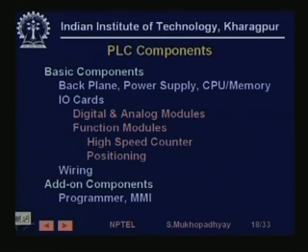So obviously there is wiring, and then you need two other separate devices with the PLC mainly for interacting with it. One of them is a programmer using which you can download the PLC program, or you can see how variables are getting changed, and the other is a man-machine interface which can display some of the variables nicely so that people can see how things are being controlled.